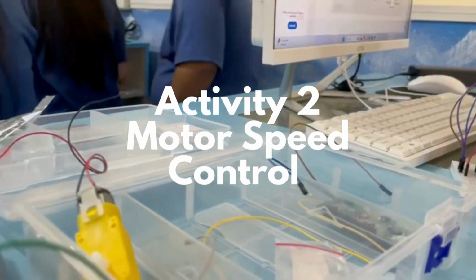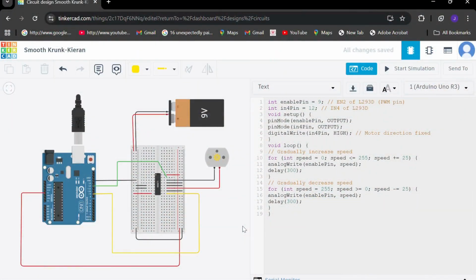Activity 2. Motor Speed Control. This activity allowed the Arduino to automatically control the motor speeds by connecting EN2 to pin 9. It was easy after following the correct wiring diagram. This is useful in smart machines that require adjustable motor speed.